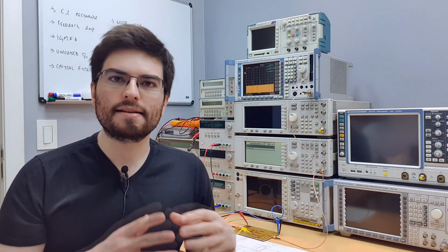But this technique can still be useful for very high frequencies, microwave bands and millimeter wave bands. In these high bands, static dividers consume a lot of power and generate a lot of noise, and this technique can be useful in this situation.